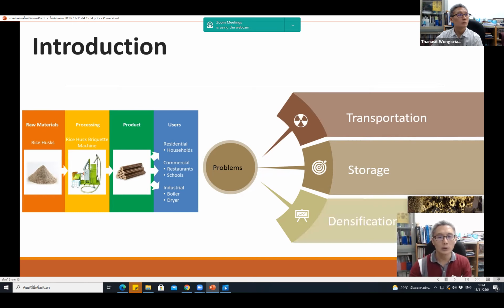Various techniques were used to enhance the quality of the fuel briquette, including mixing and varying the biomass ratio. Biomass density was affected by the material properties and compaction conditions such as temperature, pressure, die angle, size, and humidity. A higher temperature and pressure could increase the density of the fuel briquette.